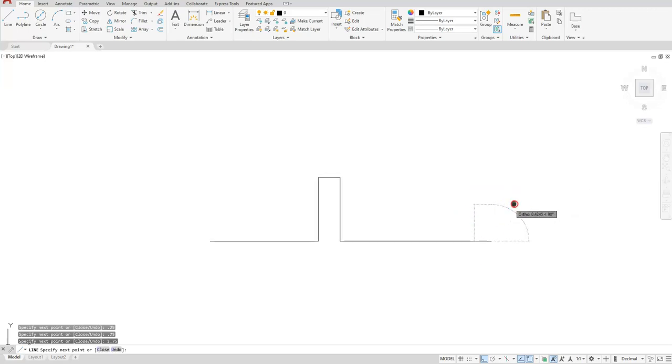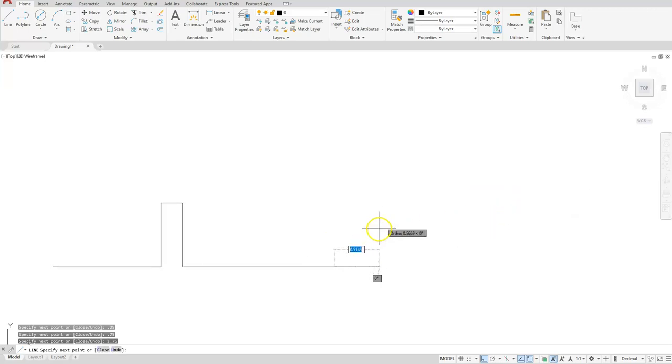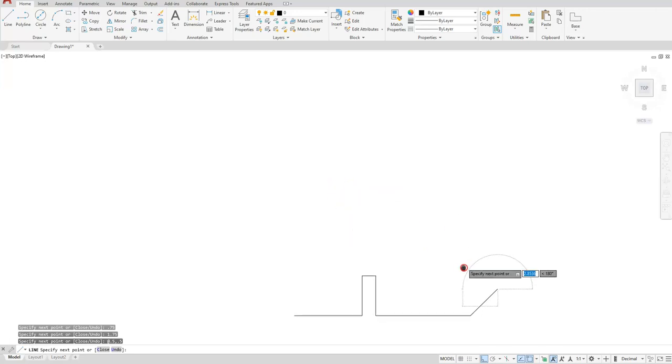Now I have to go up at this angle to make our angle line here. And if you remember back to the relative input, that's what I'm going to use to get me to that distance. So I'll type in 0.5, comma, 0.5, which happens to be the two distances that I want to go. So I want this line to go 0.5 to the right and also 0.5 going up. Once I hit the enter key, you'll see that I did make that line going up that distance.